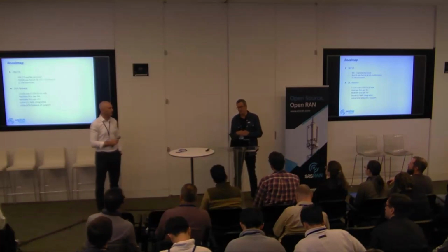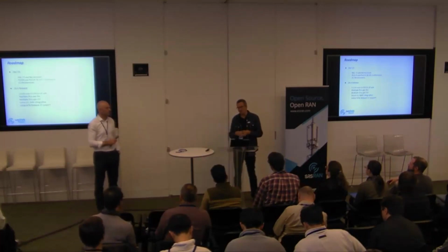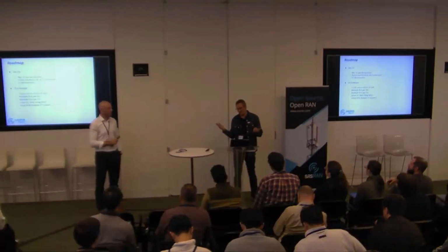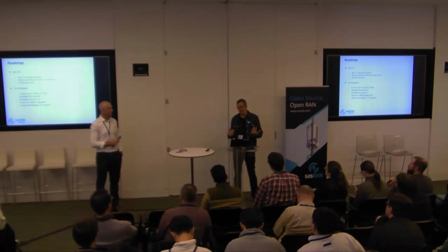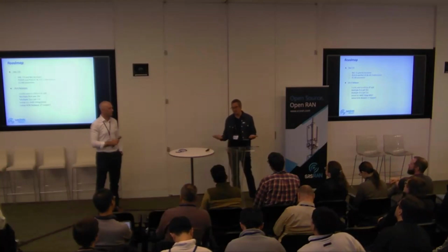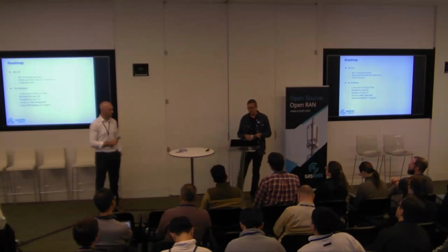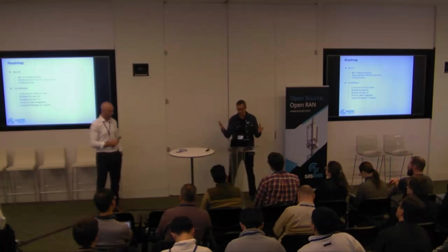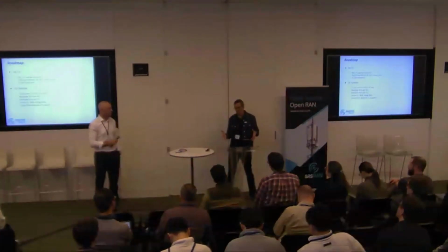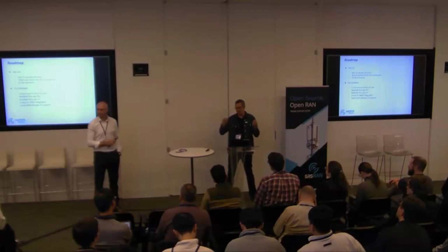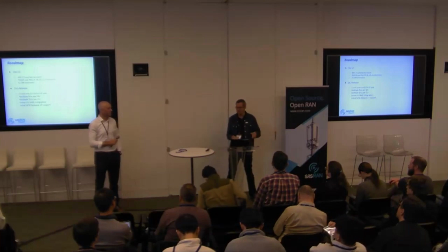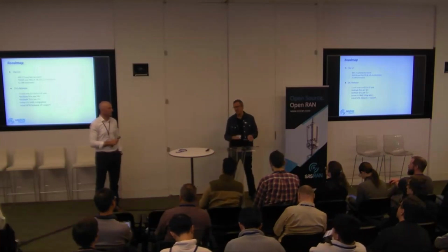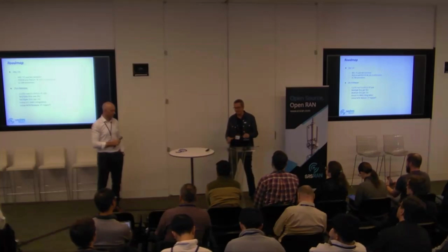If you try to test a big feature by connecting a phone to the gNB, it's very likely that out of every 100 nights you run it, a few will fail. Even trivial things matter: you have a shield box, but no matter how good it is, it will still receive some interference from outside, and if the cables you connect with the RF are not properly isolated, it will receive interference.